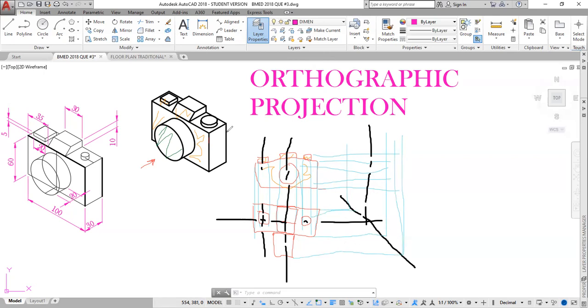So the end is what we would see looking from this side. It's important to note that what you see on the left side of the front, you could draw on the right. That's a general rule for first angle projection. So this now would be like that, and this is really not proportional. This is a little bit too wide, but it's okay, work with it.